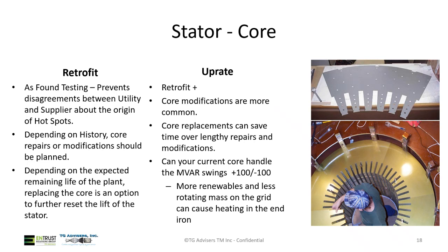In the electrical steel, the circulating current might move to the next short, and you don't know how many you have, because the one showed up on the LCID or loop test or ring test, and you didn't even know about the other ones. So you could end up with long repairs.